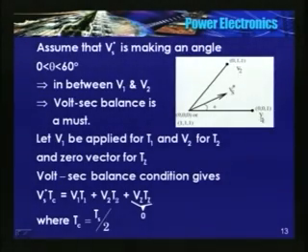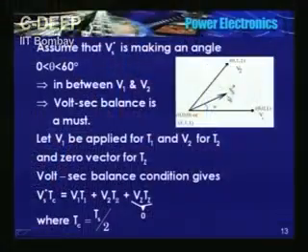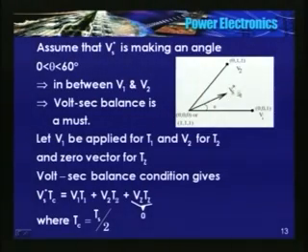When I am switching 0, 0, 1, or when you use this vector V1, the space vector is along the x axis and the magnitude is again constant, VDC. So definitely it will produce some incremental flux, but the direction is different from the direction of the incremental flux produced by Vs at the required position.